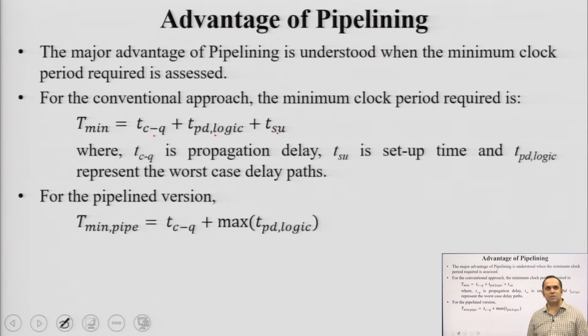By worst case we mean the maximum amount of time it is going to take. First it is going to pass through an adder, then through an absolute value calculator, and then through a log. Okay. So, all the delays of each stage add up, right,